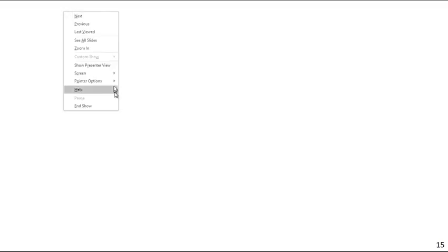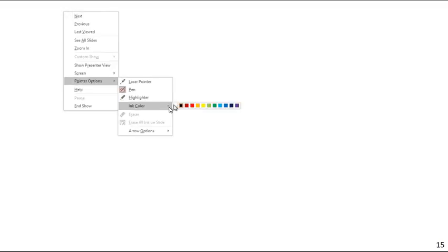After that, it's fairly straightforward to find my stresses, just using the elastic shear stress equation for torque. So tau aluminum max is going to be equal to T, the torque in the aluminum, times rho, the outer radius of the aluminum, over J, the polar moment of inertia of the aluminum section.